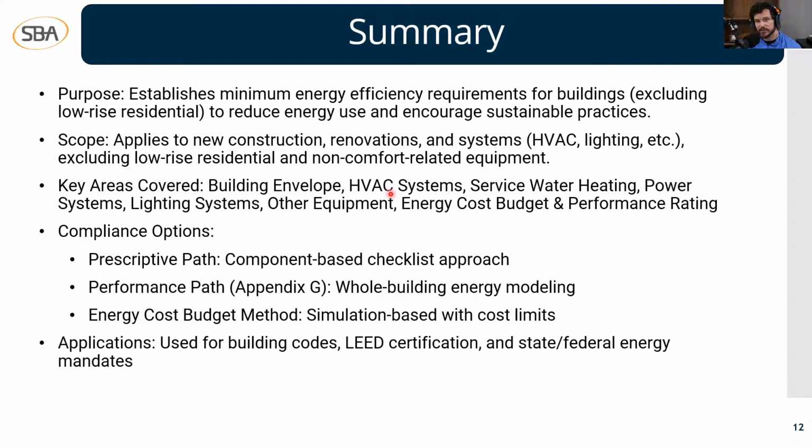We have our lighting systems. So we talked about scheduling with lighting and areas that might just need to be turned off if it's after hours and no one's in there. Scheduling is very important for ASHRAE 90.1. Also dimming in certain lighting areas. We have other equipment, which we talked about earlier.